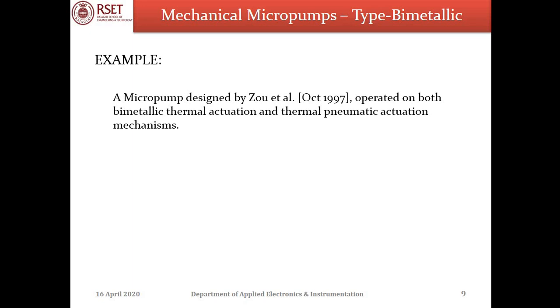What happens is this will induce thermal stress because the coefficients of the metals differ, providing a means for actuation. The implementation is extremely simple and large forces are generated, but the deflection of the diaphragm that can be achieved by thermal alternation is small.